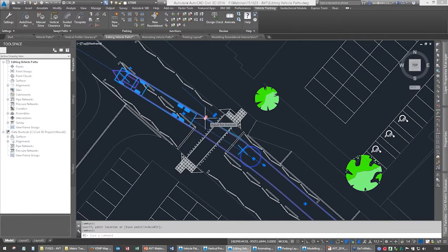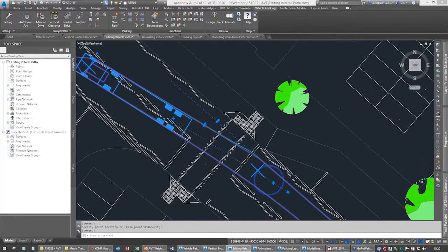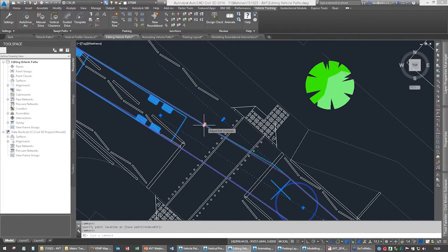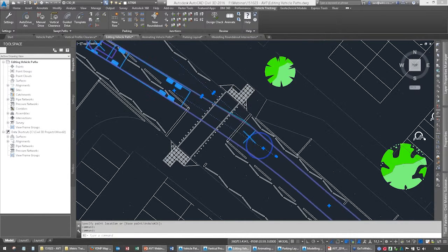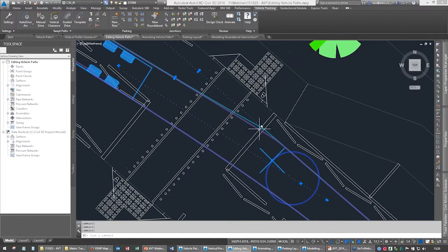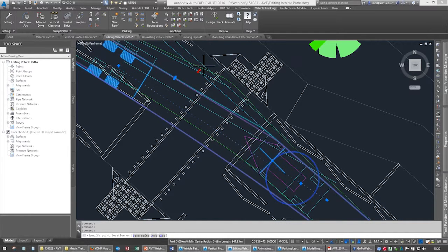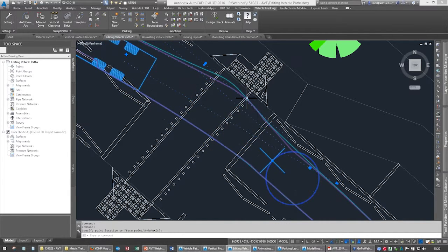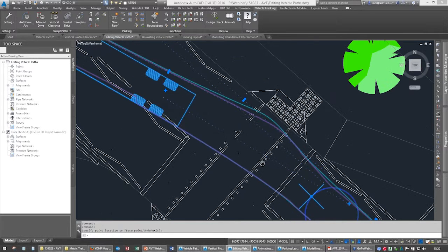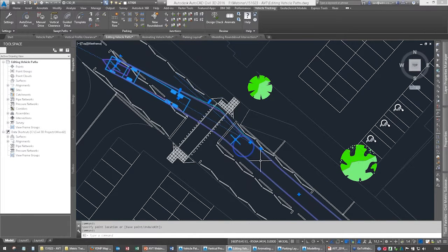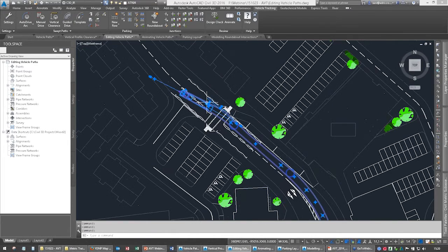But once you've got your bearing, look, we can now adjust that bearing, and we can adjust using these grips here. So we have these additional grips here for adjusting the overturn and adjusting the side overturn. So you can see it draws these lines here. So that's my side overturn there. So if I wanted to adjust that, I can bring that across towards the edge of my junction, and that allows it to dynamically update the vehicle swept path analysis, which is quite nice.